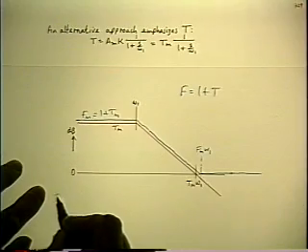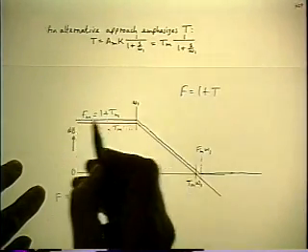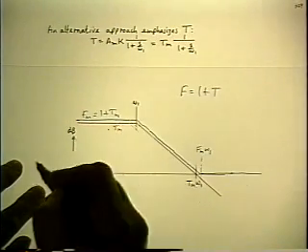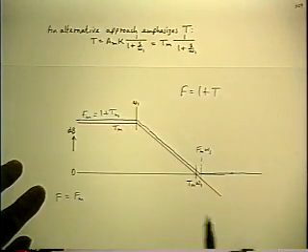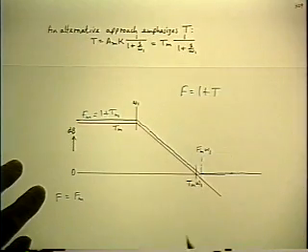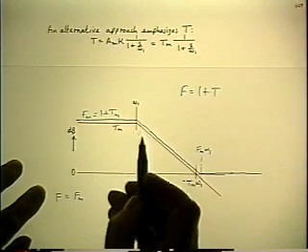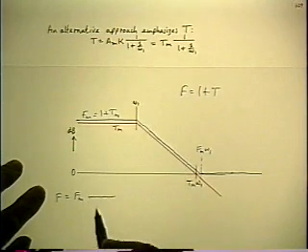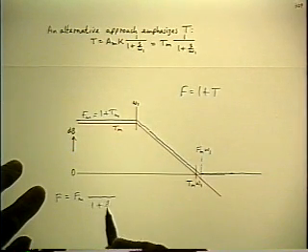So you write it, F equals the low frequency flat value, which is Fm, and then you look down and look up in frequency and see what happens. If you look down, nothing happens. If you look up, you see a concave downwards corner, which is a normal pole at omega 1.